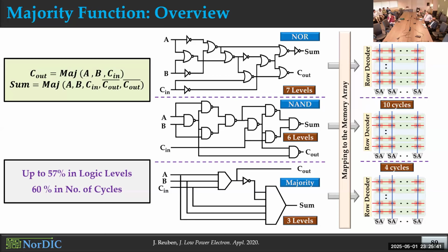Yes. So it's pretty common there, but I'm curious about the attraction to NOR and NAND. Those are computationally complete in the digital world, and so you can readily describe it at the RTL level. So what about this majority scheme? Does that still translate at the RTL level? Yeah, there's a hardware restriction. Majority with an inverter is also considered functionally complete. If you have an inverter and majority logic, you can implement any Boolean logic function. Okay, that's what I was just checking.